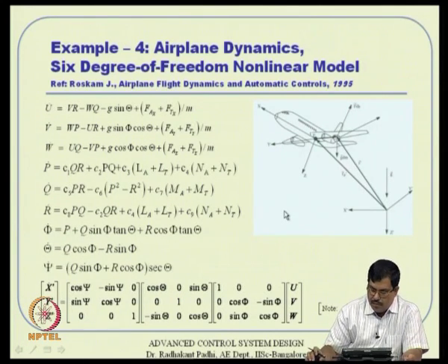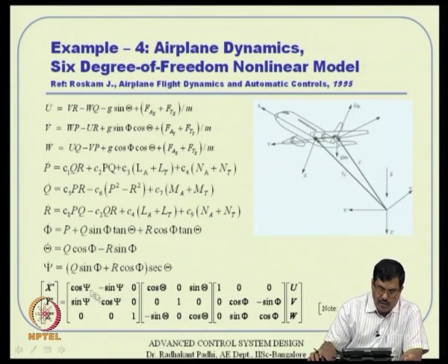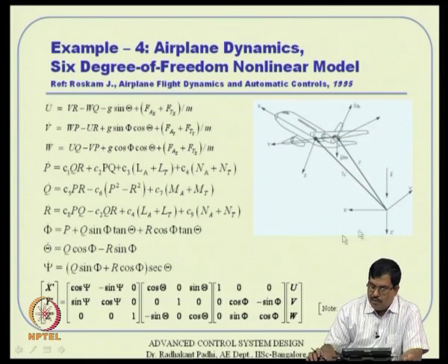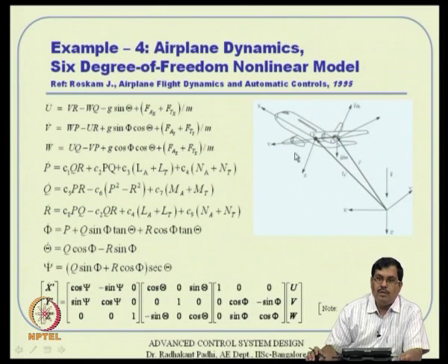We have observed in the flight dynamics lecture as well that 3 equations are really decoupled from the rest of the things, and these are psi, x and y. If you take out these 3, then you are left with 9 equations. Out of those 9 equations, you can visualize a perturbation around, let us say, straight and level flight. Height is known to us probably, so that means height is also gone. So, you are left with 8 equations, and we can linearize those, and that linearization also leads to decoupling of the system dynamics into longitudinal and lateral. Let us quickly review that.